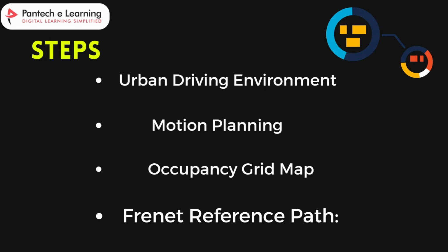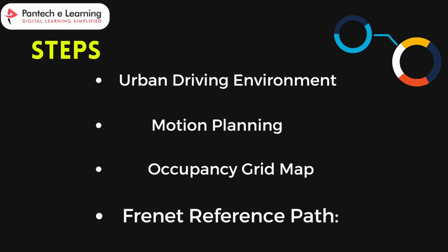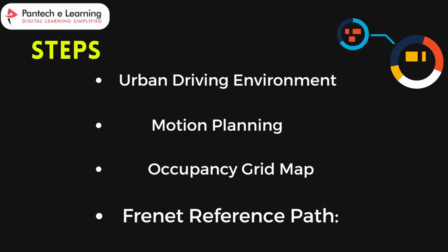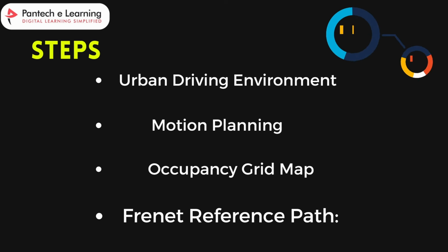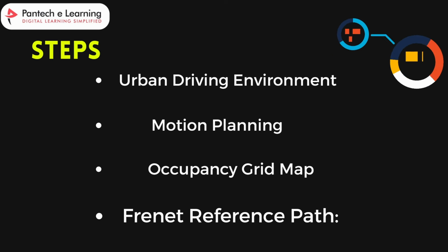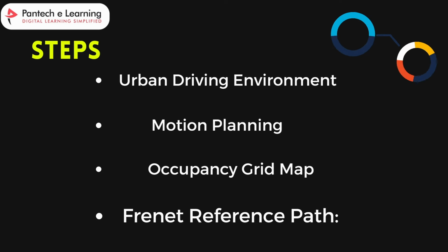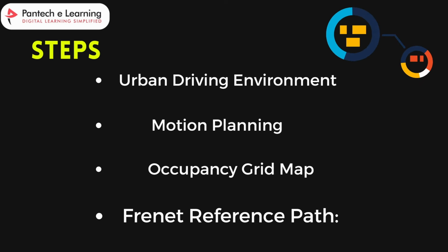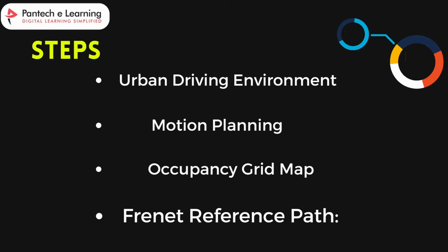Next one is the Frenet reference path. This is the main thing we are going to discuss today. So what is this Frenet reference path? It is a parametric representation of the desired path for the vehicle to follow. It consists of two components.